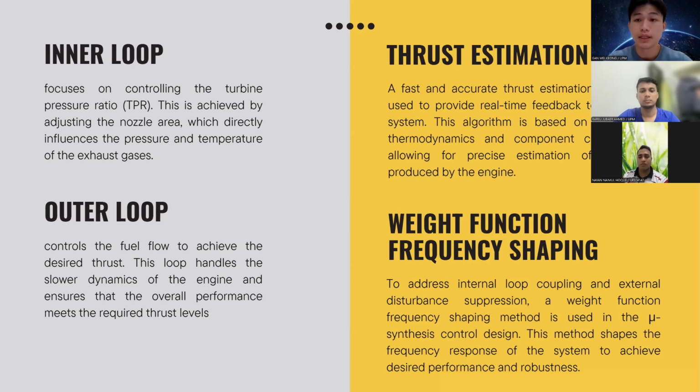For thrust estimation, which is the third component in this control strategy, a fast and accurate thrust estimation algorithm is used to provide real-time feedback to the control system. This algorithm is based on aerodynamic and thermodynamic component characteristics, allowing precise estimation of the thrust produced by the engine. Let me pass to Rafiu to explain the next part. Thank you.